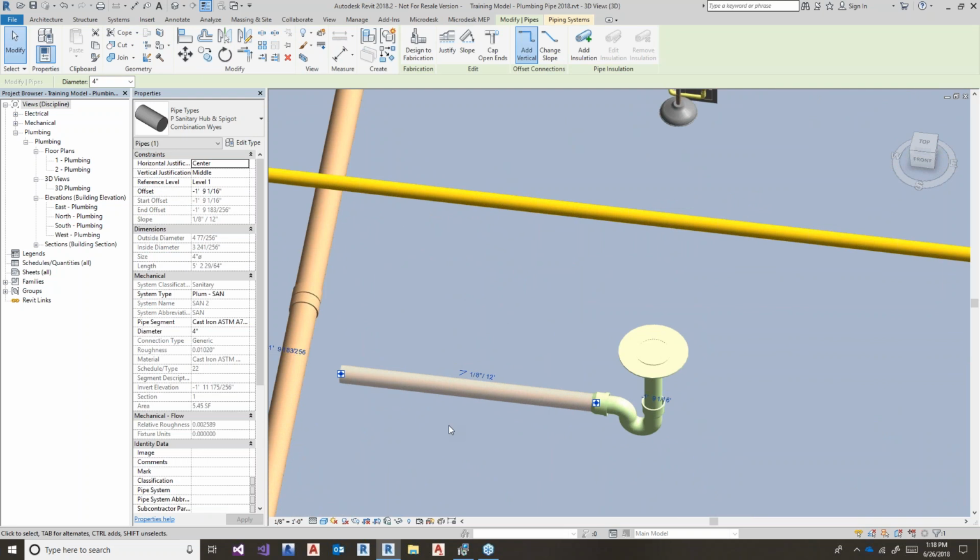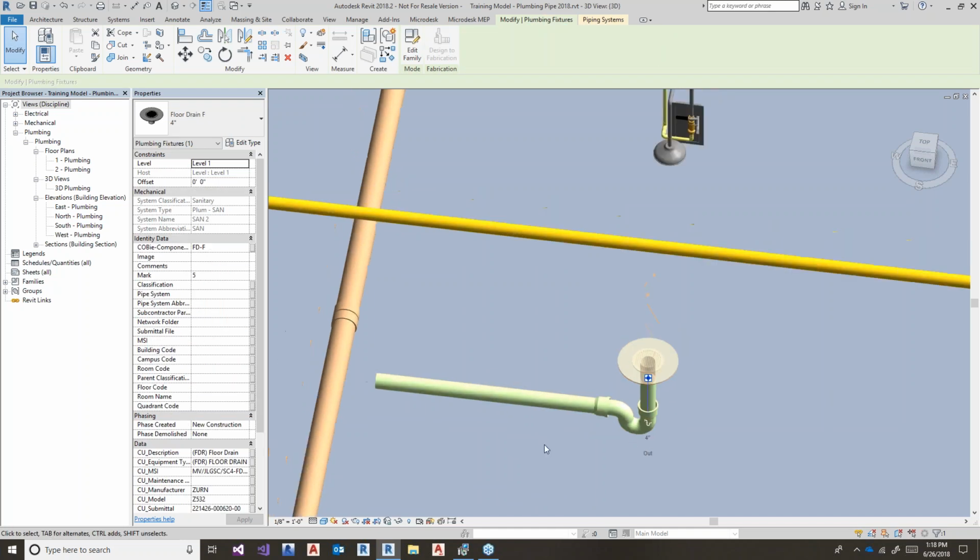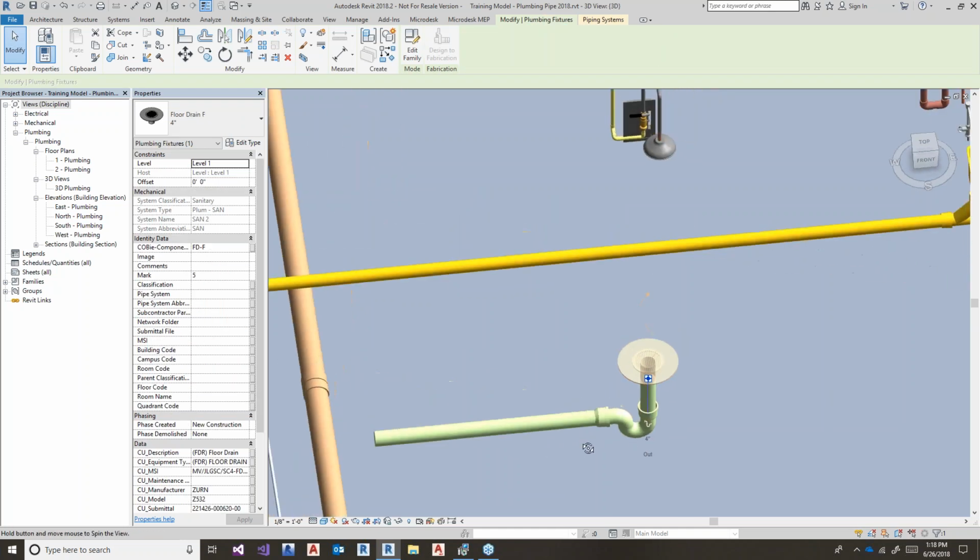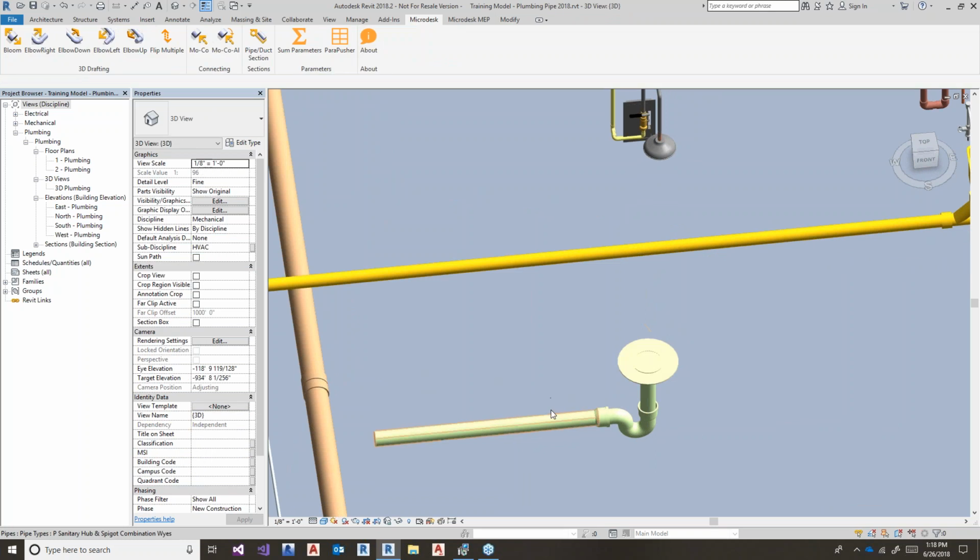We're going to pay very close attention to the slopes, because one of the biggest frustrations we hear from folks is that after they start editing sloped connected pipe systems, the slopes inexplicably change. So we want to make sure that the tools aren't going to affect any of the slopes that we've already drawn. Once I've got my floor drain and P-trap in, maybe before we connect any further, I might want to put a vent line in.